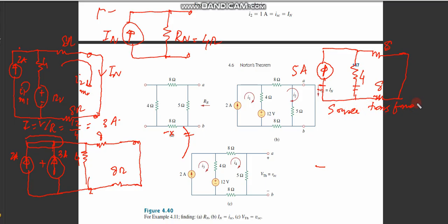method. So I can convert this into a voltage source. To convert into a voltage source, I would have a voltage source with the plus over here, minus over here, because plus is at the upper portion. And then I would have this 4 ohm resistance connected now in series. And then if you see, I have this 8, and then I have it again. So basically this is a circuit now. Value of this is 8 again.